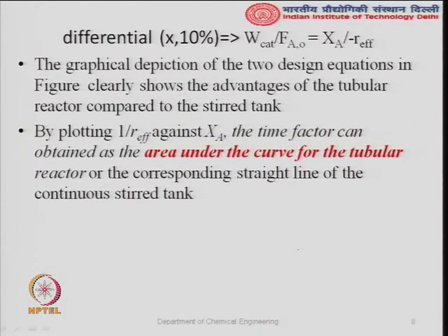So, this is what we have discussed now, that when you do the kinetics in the differential reactor, you have to make sure that conversion should not be more than 10%. At the most you can go with 15%, but the lower the conversion, the better the data, because your assumptions are more valid there. Uniform composition throughout is very important, when C A is equal to C A naught (1 minus x A), or an expression like this which you are devising.